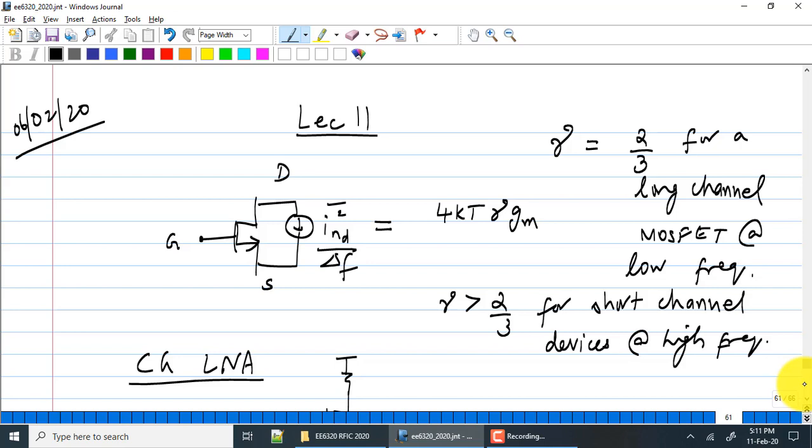You just need to remember that in case sometime in the future you go in and look and say, hey, I expected gamma to be specified, it's not specified. Flicker noise, I expect KF to be specified, it's not specified. You need to go back and look at the ways of modeling this. You'll find that there is some noise flag that is set such that this noise is modeled differently.